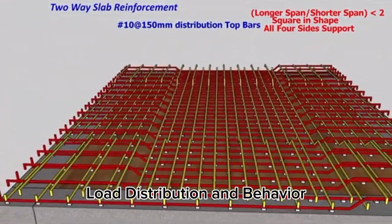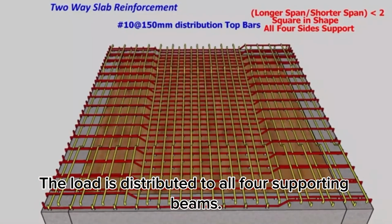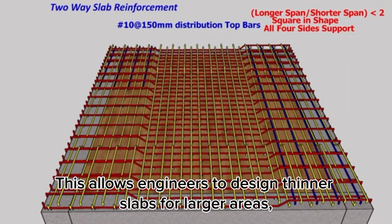Load distribution and behavior. The load is distributed to all 4 supporting beams. Because the slab is resisting bending in 2 directions, it is inherently stiffer than a one-way slab of the same thickness. This allows engineers to design thinner slabs for larger areas.